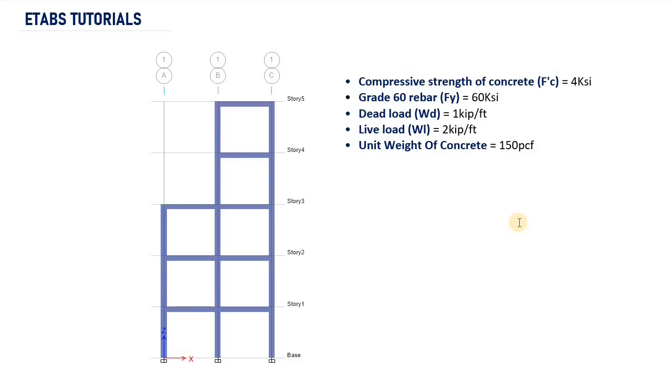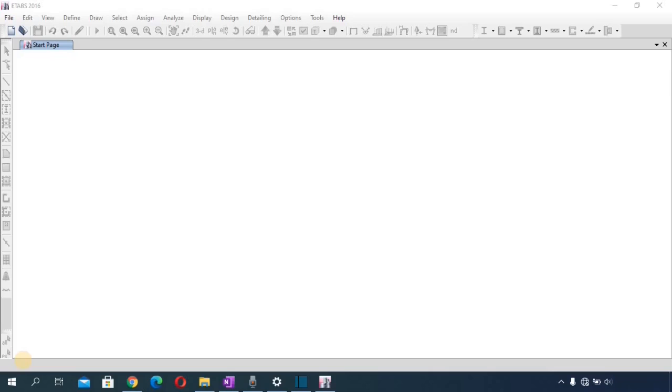Now, this is the unit weight of reinforced concrete, because we know that the unit weight of reinforced concrete is a little bit higher than the unit weight of concrete itself. When we cast concrete, we usually have reinforcement steel, and we also need to account for the unit weight of the reinforcement steel. Because we account for the unit weight of reinforcement steel, we tend to bump this up. That is why we have 150 pounds per cubic foot.